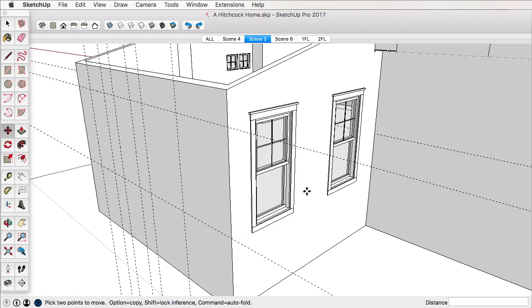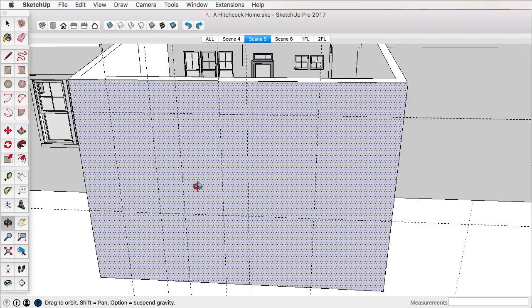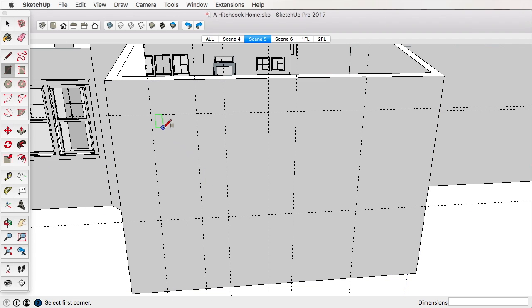With the DoubleCut plugin, you can essentially use that Glue To property and the plugin will automatically create the opening for you. So let's take a look at how it works. I'm first going to draw a rectangle, and let's first just look at it purely as a way to create a cut opening. So not so much as taking an existing Glue To model, but more of just actually how to use it purely for an opening tool.